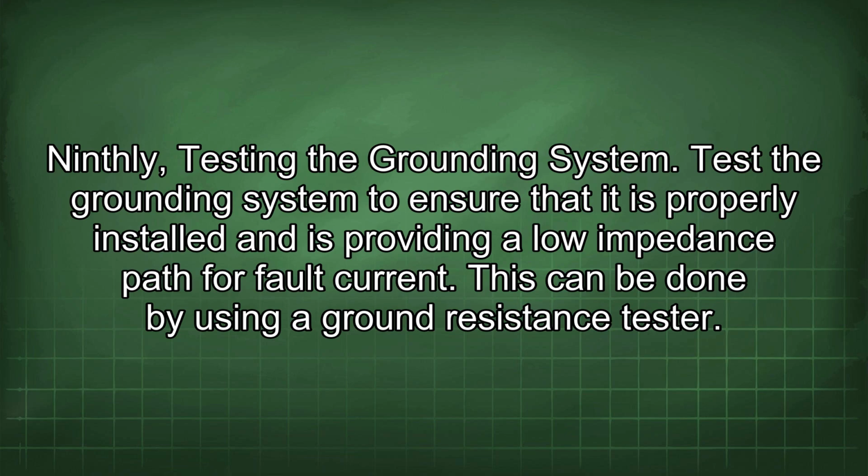Ninthly, testing the grounding system. Test the grounding system to ensure that it is properly installed and is providing a low impedance path for fault current. This can be done by using a ground resistance tester.